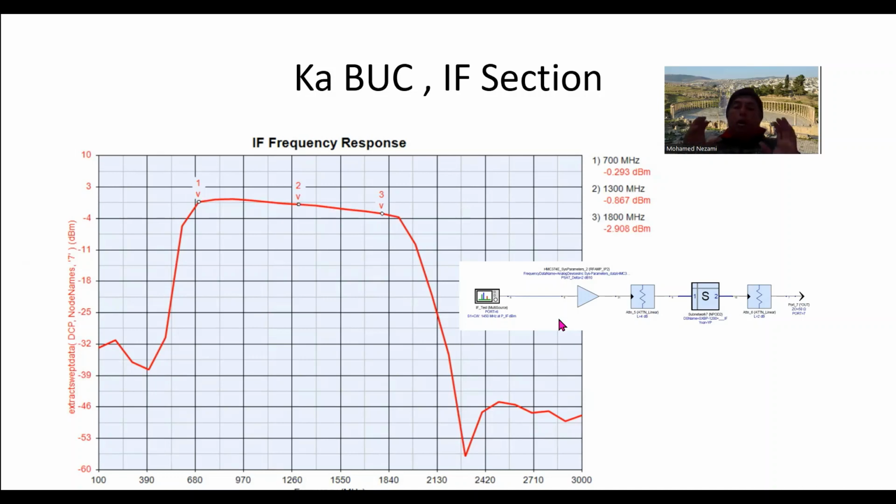Now, how do you fix that? Right now, we're not going to try to fix that, but we fix that with equalizers, just a very simple passive combination of lumped components. We do that once we start the schematics, we include that in there. So we just make sure that we have some kind of, say, a series inductor that will have a slope that is opposite to this, and it equalizes that, okay? But we have to wait until we cascade the whole thing at the schematic level, and that's where you would model it again, including all the passives and the biasing in ADS, of course.